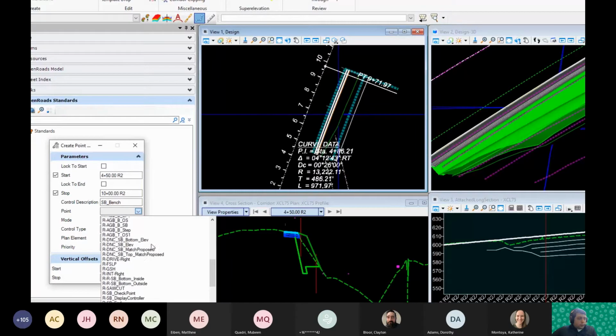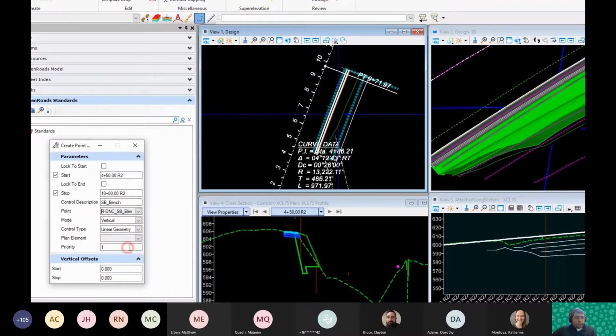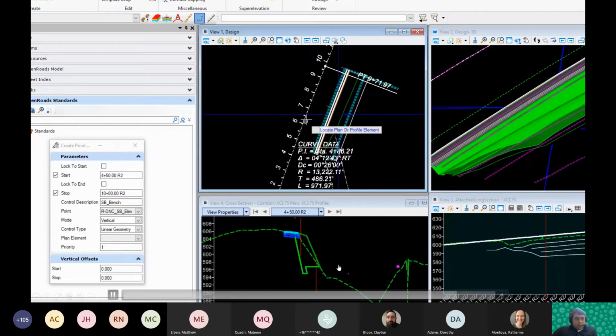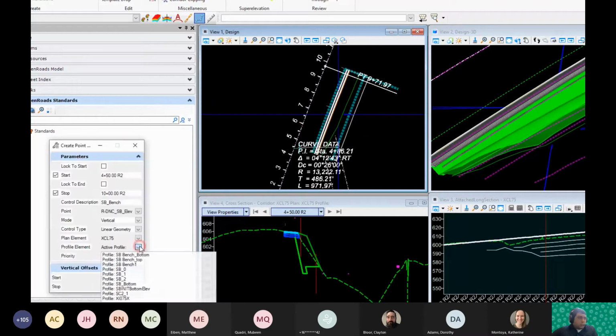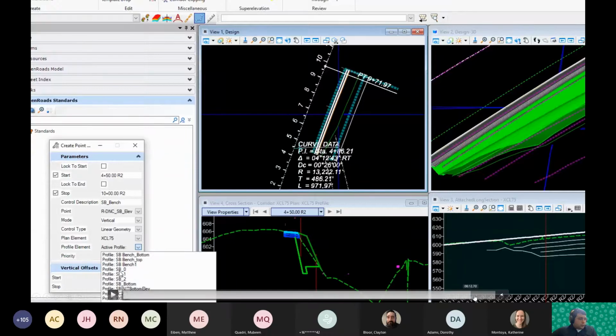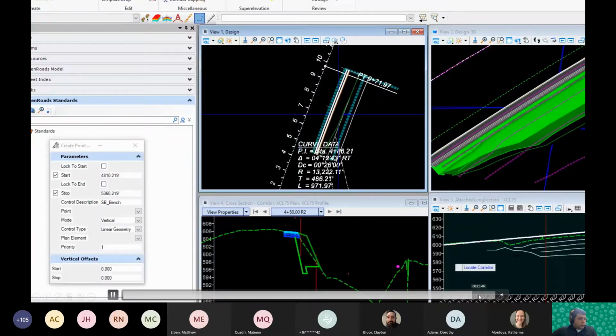But so I come down here and I want that elevation point, right? So as I add more benches in, I'd see elevation 1, elevation 2, kind of in that order. I tried to set it up so that when you just add some in, the auto numbering on the templates doesn't get in the way. But so after I add this, I'll select my profile. Jump forward a little bit here.